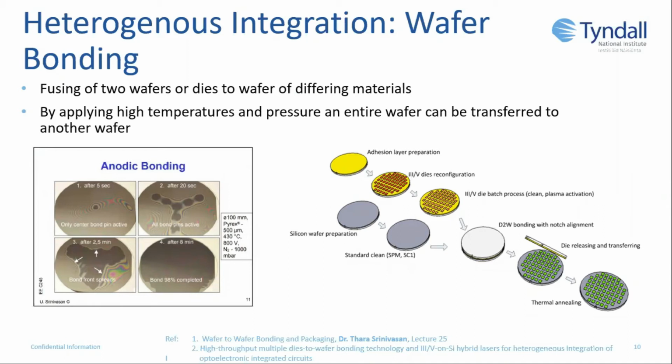To the right here and in the previous slides, both of these are examples of adhesive bonding. Adhesive bonding is when there's an intermediate layer used for the bonding. Generally, the choice of material for this layer depends on the substrate material and the topography. Polymers are commonly used, with DVS-BCB being a popular choice as it doesn't create unwanted byproducts when it's cured. The advantages of adhesive wafer bonding are that it's low temperature processing and the surface planarization, so you have a smooth surface after bonding.